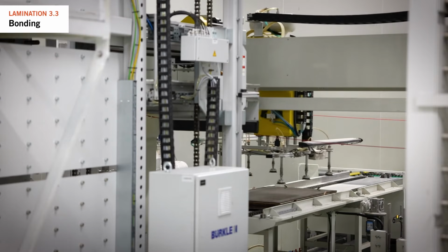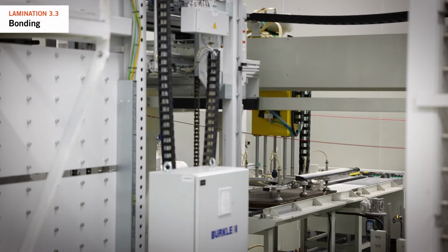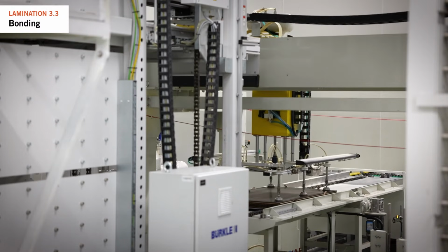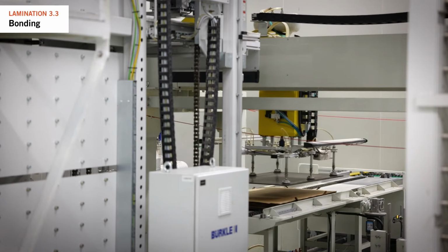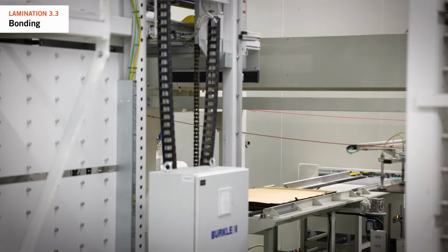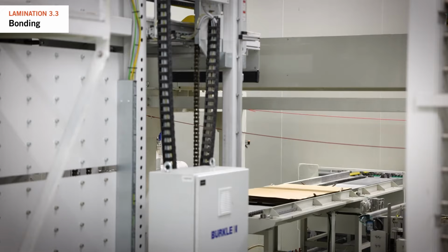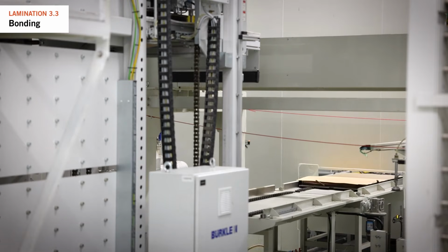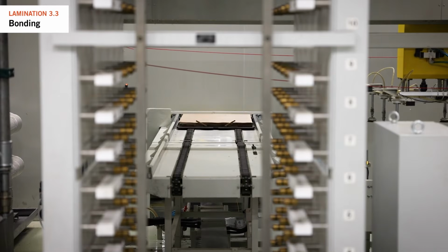Lamination is a crucial step in multilayer production. To pass the NCAB audit, each factory must show they have press parameters for various materials and constructions. Additionally, they need to prove through reliability tests that the bonded panel can withstand specific forces or pressures without coming apart.